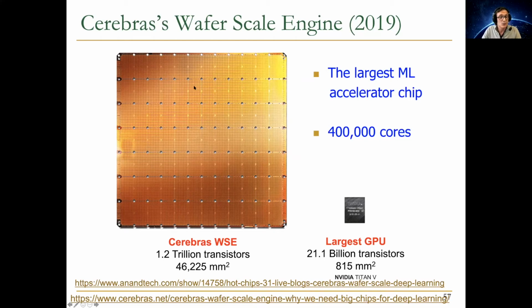Well, these folks at Cerebras designed a chip and a machine that's much bigger. The chip itself, you can see that it's 46,000 square millimeters. It's a wafer scale engine. So normally you start with wafers, you cut it into pieces, and those pieces become your chips. These folks said, no, we actually want a chip that's much more capable. We want to accelerate these machine learning training workloads so that we can form the model.